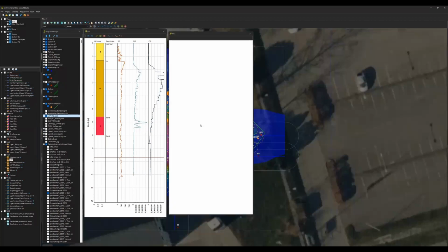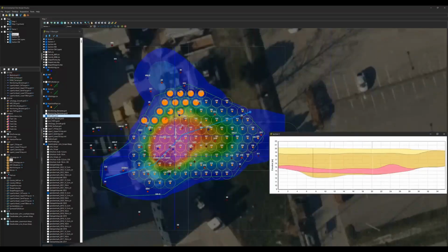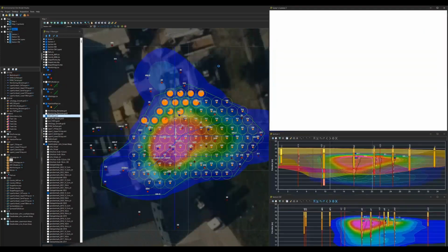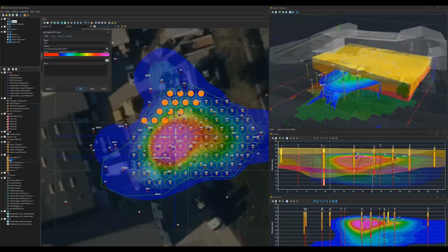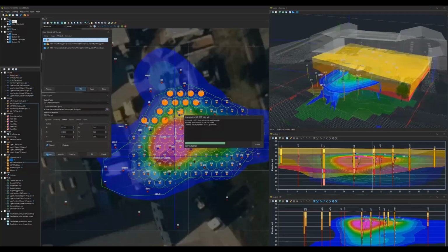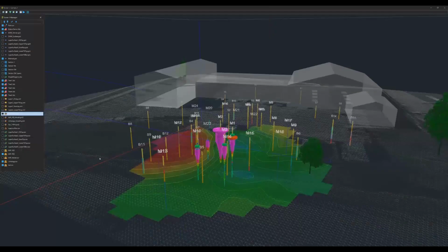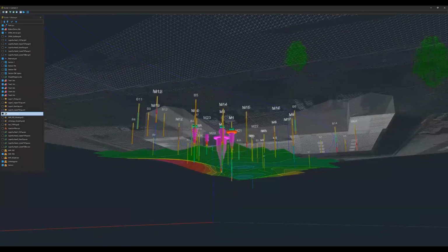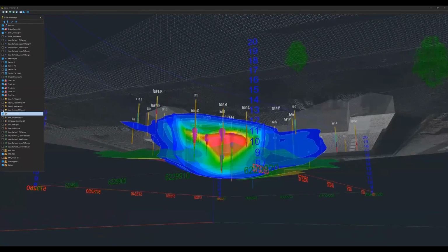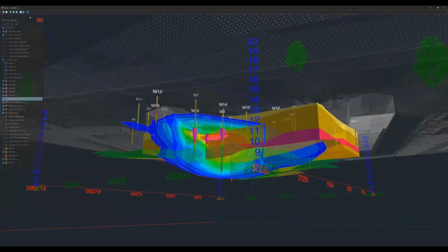Yes, so what pre-drilling means is that when using direct push technique, one of the main challenges of direct push is, for example, dry sands, because they create so much friction around the pipe. So in those kind of challenging geologies, just because you cannot advance direct push in the first place, you shouldn't just give up. So in that case, what we were able to do was to advance a rotary rotopercussion tooling down to the targeted depth. In that case it was about 15 to 17 meters, depending on the area at the site.